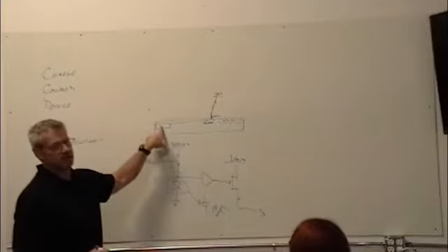You're swinging voltages back and forth at high stresses. There are stupid, weird voltages that CMOS doesn't like, right? Minus 12 volts, you're back to BJT processes a lot of times. You have to do level shifters to get from what your computer uses, which these days is like 0.3 volt, hell, for some of them it's 1.8 volts coming off, right? And so you've got to level shift 1.8 to 0 to 5 to minus 12.